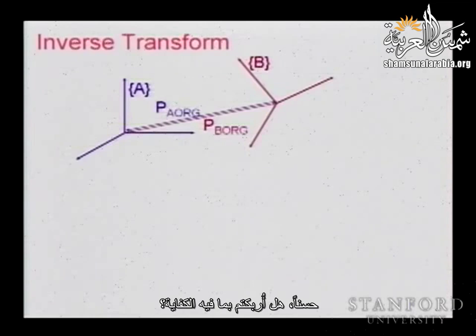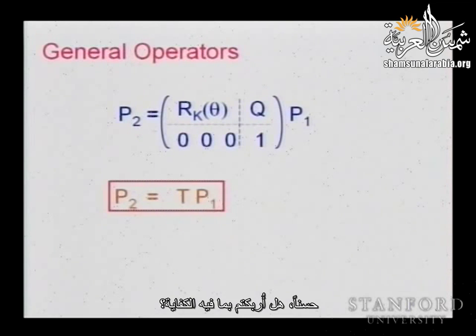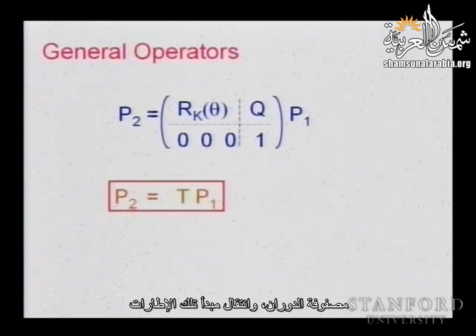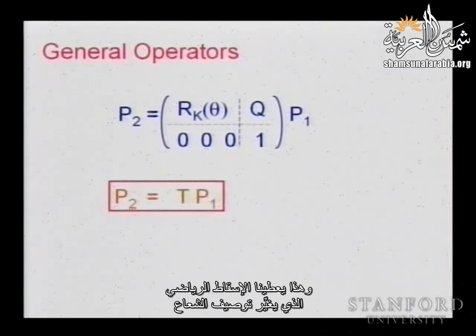Okay. Are you confused enough? Good. So two things. We saw the transformation. It is the same homogeneous transformation that has two components: rotation and translation. The rotation matrix and the translation of the origin of those frames. That can give us mapping, changing the description.